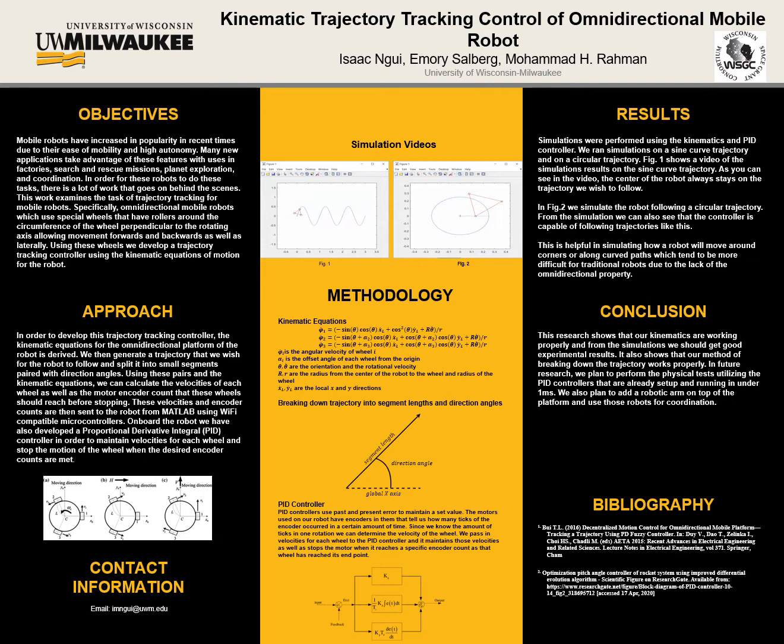So using those, the first term on the top is Kp, which is proportional. The middle term is going to be our integral, and the last term is going to be derivative. And using a combination of those three and summing them up, we'll be able to push our set velocity that we want to move at, so 60, and we'll push whatever we're outputting up until it meets that 60 and stays there. So it won't go higher and it won't go lower than that value.